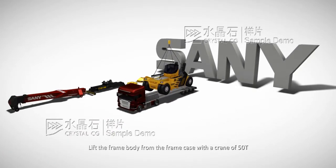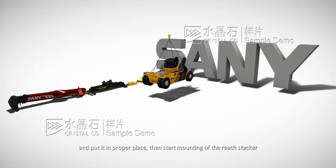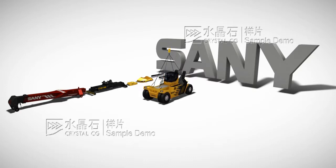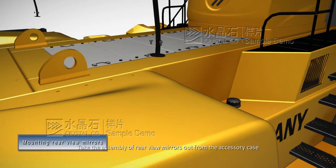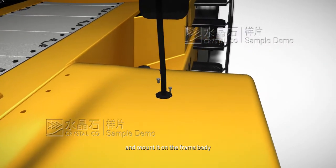Lift the frame body from the frame case with a crane of 50 tons, and put it in the proper place. Then start mounting of the Reachstacker. Take the assembly of rear view mirrors out from the accessory case and mount it on the frame body.